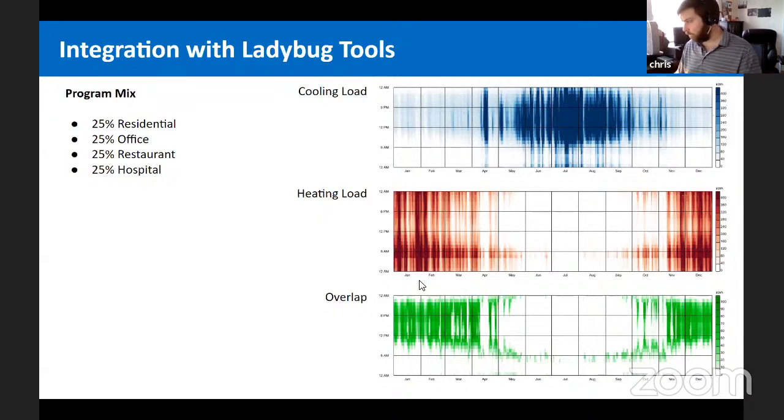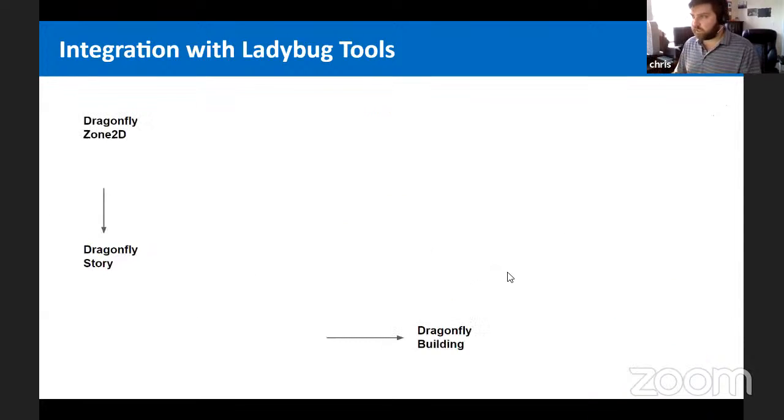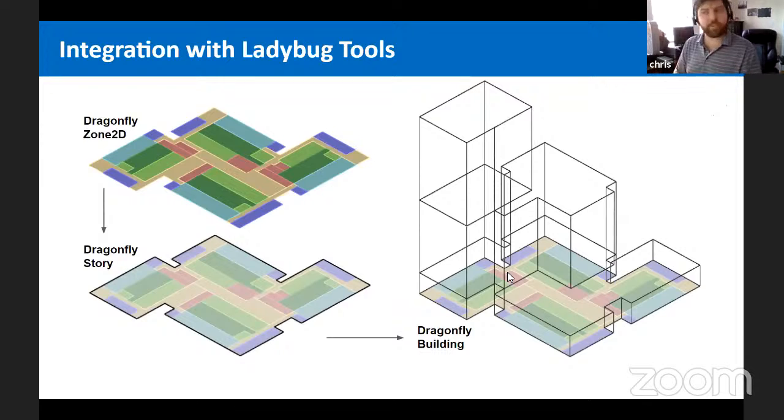Okay, so briefly, I'm just going to go over the very last workflow, the most detailed workflow that we put together for the Grasshopper plugin, and explain a little bit of how the Dragonfly building schema is structured, and what's been done to it in order to optimize it for the urban scale. So essentially, at its core, all Dragonfly objects are represented by 2D floor plates.